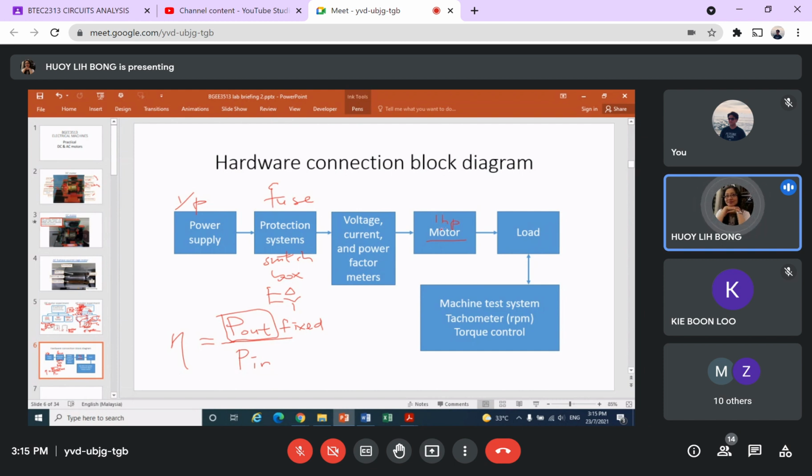So the efficiency that you measure must be at 1 horsepower, according to the output rating. We say the rating is always the output. A customer buying a 1 horsepower motor means, of course, this is the output they want, not the input. They are not interested in the input.